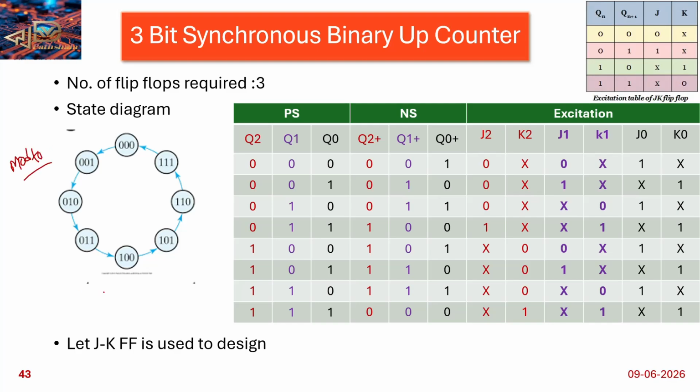That means starting from 0, with 4 bits, we count 0000, 0001, 0010, 0011, 0100, 0101, 0110, 0111, 1000, 1001. Whenever it reaches 9 and then the 10th position, it is again going to 0. So that is a modulo 10 counter, because counting 0 to 9 is 10 states.